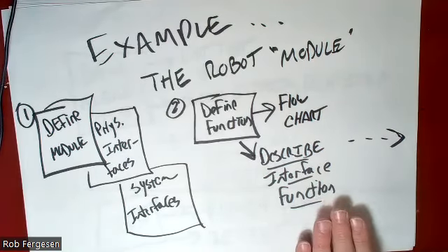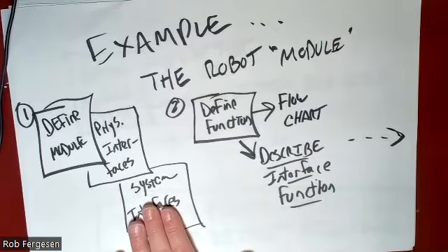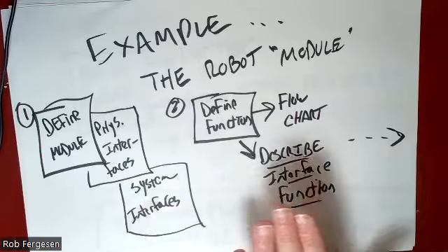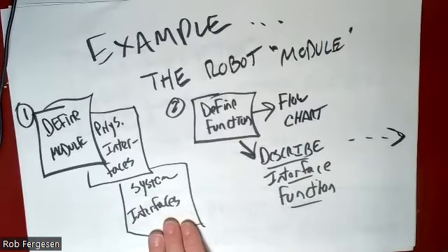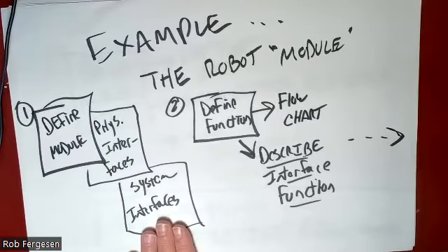And generally speaking, you will write one interface per system interface. In terms of I/O, it means you're going to have one description per point in that I/O list. Now, not all system interfaces are I/O. Some system interfaces will be through Ethernet or other communications means like Modbus.